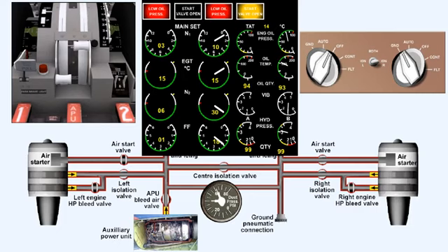To prevent torching and excessive EGT, before attempting a second start, a motoring over or blowout cycle must be carried out. So, immediately the wet start is diagnosed, do not terminate the start cycle. Instead, promptly shut off the high-pressure fuel supply and deselect ignition, and then allow the starter to continue to turn the compressor for the time remaining in that start cycle before attempting a blowout cycle. These actions will allow the compressor to start blowing out any fuel from the engine even before you carry out the blowout cycle proper.